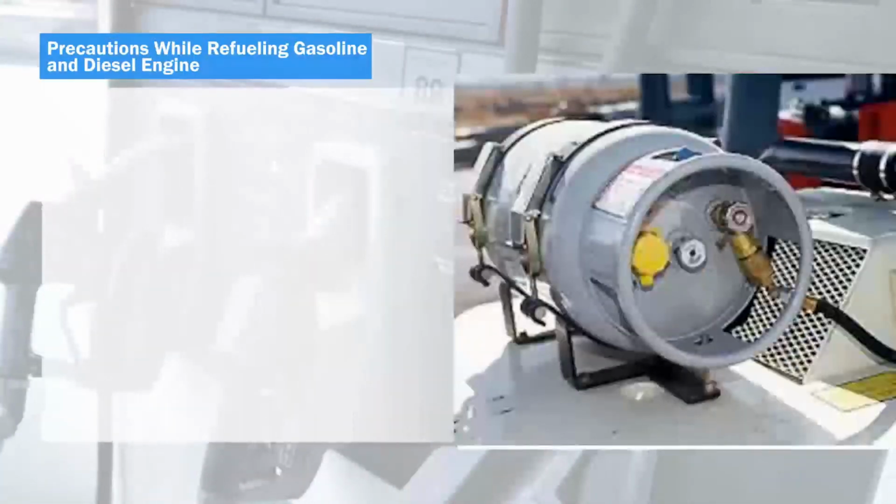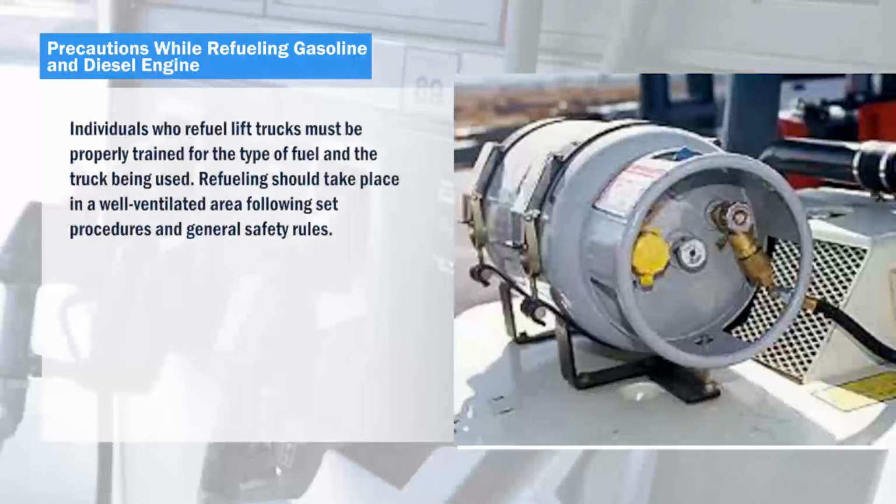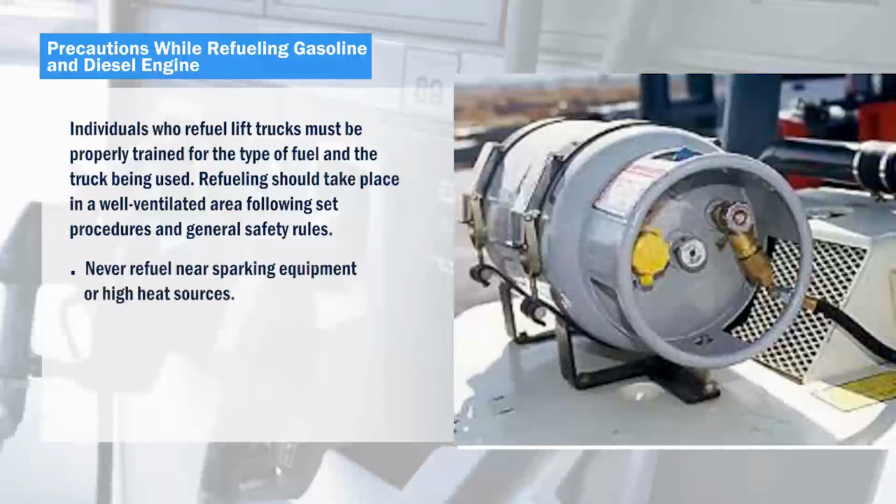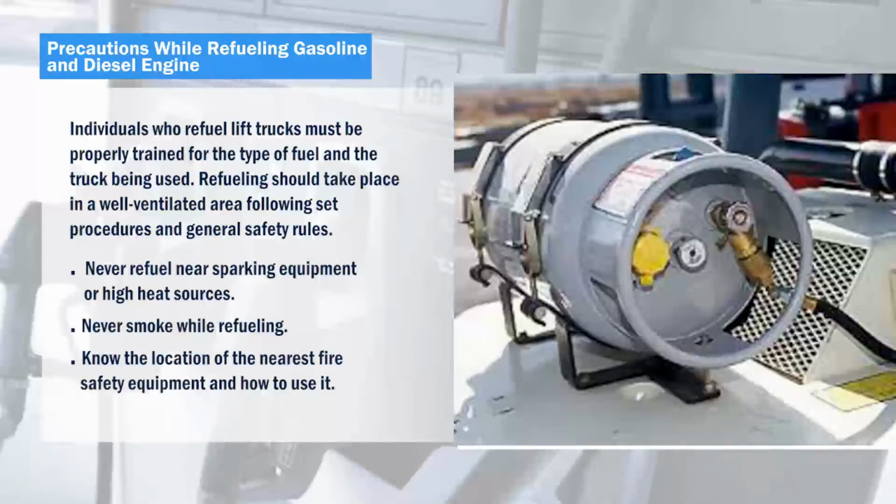Precautions while refueling gasoline and diesel engines. Individuals who refuel lift trucks must be properly trained for the type of fuel in the truck being used. Refueling should take place in a well-ventilated area following set procedures and general safety rules. Never refuel near sparking equipment or high heat sources. Never smoke while refueling. Know the location of the nearest fire safety equipment and how to use it.